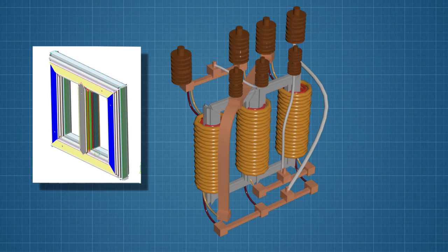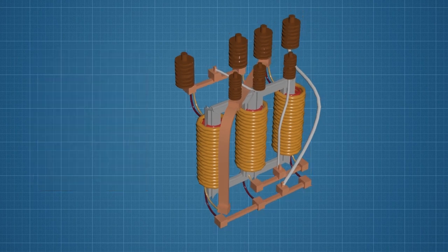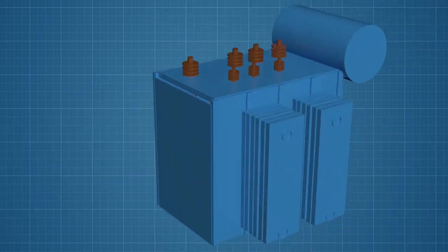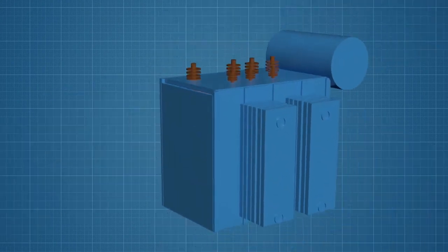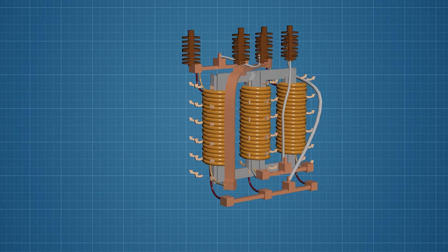The magnetic core is made from thin insulated steel plates. Laminated assembly is used for improving the performance of plated magnetic cores. Its principle is based on clear distribution of layers and creation of equal gaps therein inside the rod and yoke in such a way that all the created cavities are filled with minimum jointing during assembly. At the same time, the plates of the rod and the yoke are intertwined with one another, forming a robust and rigid structure. The laminated structure of the magnetic core allows reducing the losses that occur when eddy currents arise.